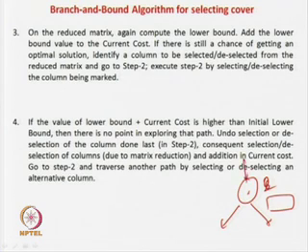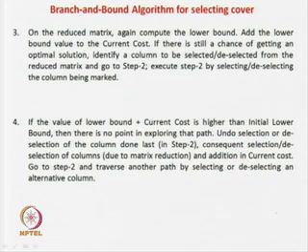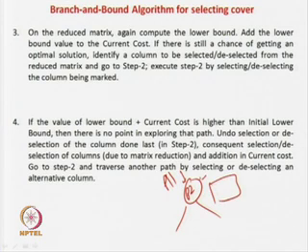we have reached here by saying that we have taken a node in this way, let us represent it in this way. So say this is a node over here and say you have reached this node by taking some P1, prime implicant 1 you have taken over here. So there can be two solutions, say this corresponds to P2, you take P2 or you don't take P2, that is how you can explore. Okay, but at this point you have a reduced matrix. By taking P1 you have done row dominance, column dominance, essential columns, you have done everything and say finally you have got a reduced matrix and it is not a terminal case.